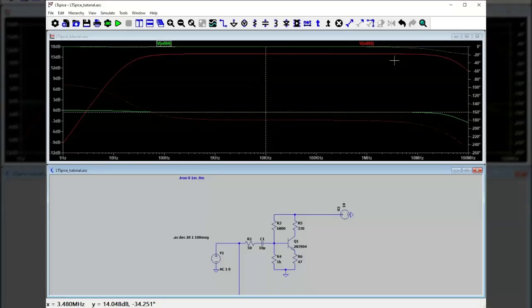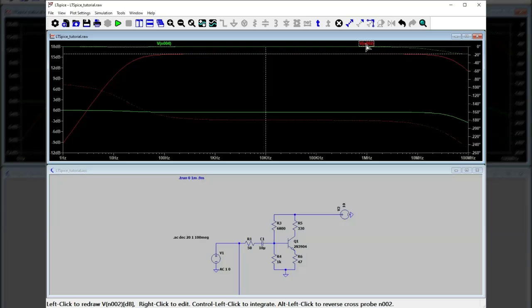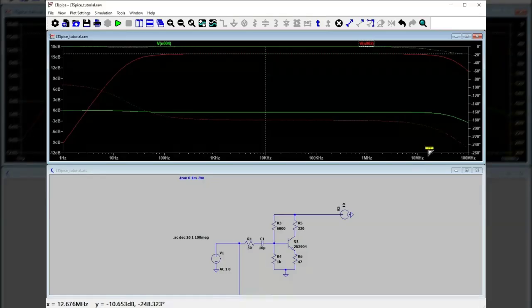And so what do we have on the output of the amplifier at 10 kilohertz? That's 15.91 dB above a volt, which is about 6 volts, 6.5 volts, I think. Okay, how would you figure that out? If you undo the dB by dividing it by 10 and then raising 10 to that power, and then take the square root. All right, that's how you would undo the dB, and that's how you get the roughly 6 volts there.